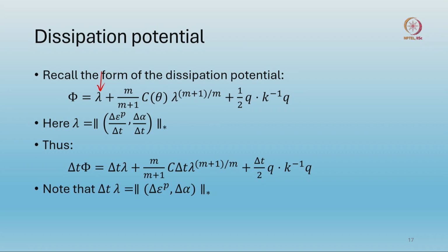The other part corresponds to the rate dependent viscoplastic part for phi. C theta contains the viscosity. That means if the viscosity parameter is 0, then C theta will also be 0. And then you have this lambda coming in here too in the Perzina model. Some aspects of that rate independent part will be coming here too, if you recall the structure of that Perzina model, and there will be a thermal part of phi which is given here, which is quadratic in the heat flux Q.